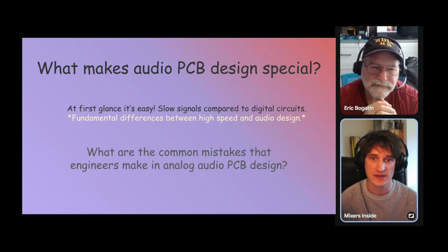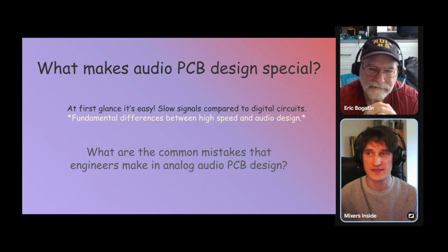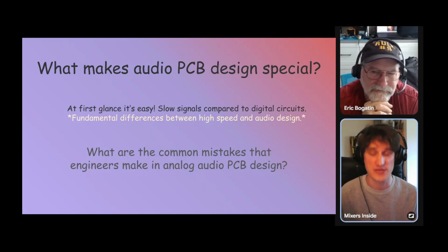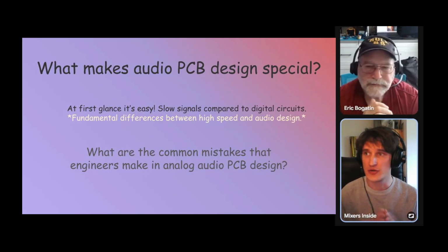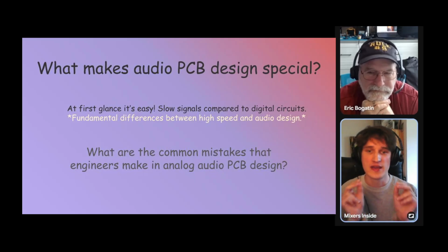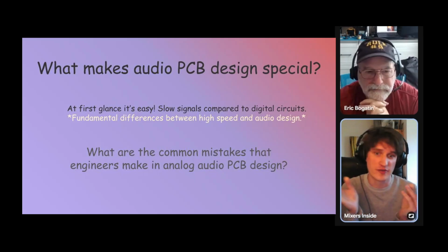Nowadays, many boards used in various devices deal with digital signals, very high-speed signals, and they require special care, like impedance, or as I mentioned before, keeping components closer to each other or far away.